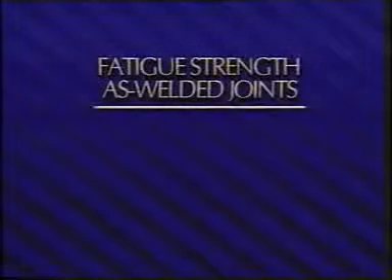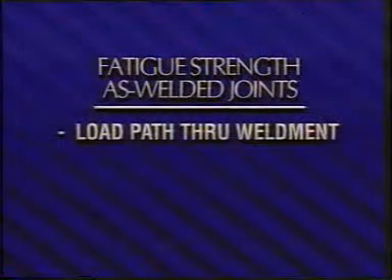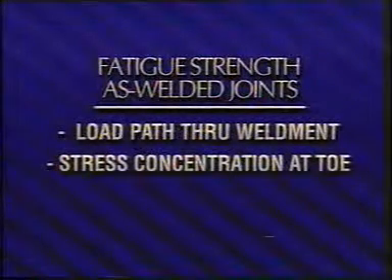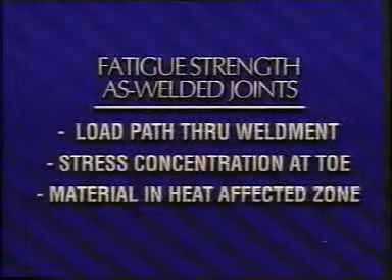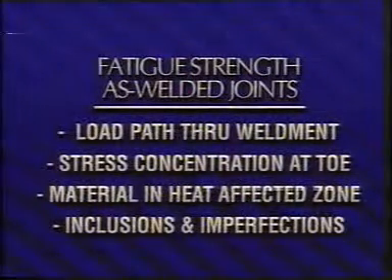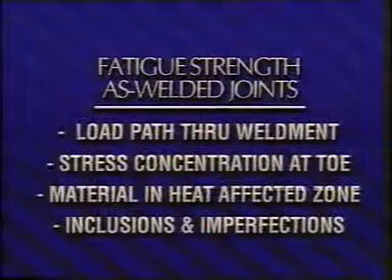The fatigue strength of good as-welded joints depends on the stress state in the load path weldment, the stress concentration at the toe of the weld, the condition of material in the heat-affected zone, and the presence or absence of inclusions and other imperfections in the weld. The fatigue strength of as-welded joints can be increased by cold working. The growth of cracks can be inhibited by introducing compressive residual stresses and redistributing fabrication stresses.